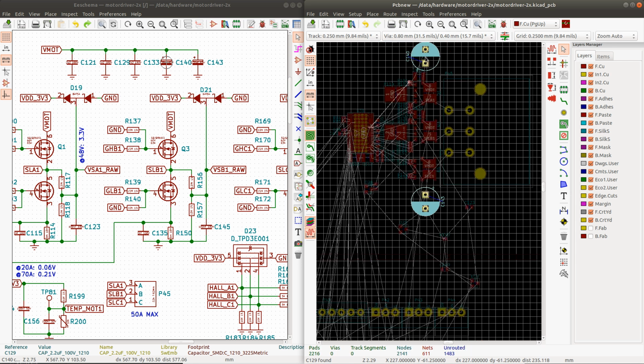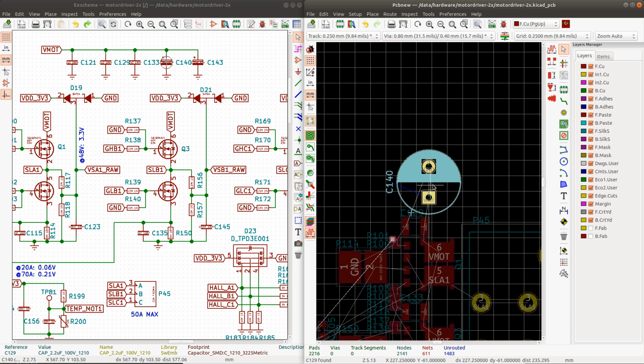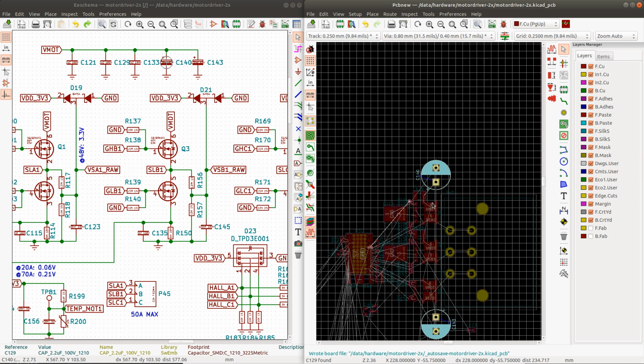And that is very good because when the load changes on the power supply, that also changes the voltage on the power supply. So any change in the current will also add noise to the power supply rails. So that is what we're trying to avoid essentially by placing bulk capacitors which can provide that current instead.